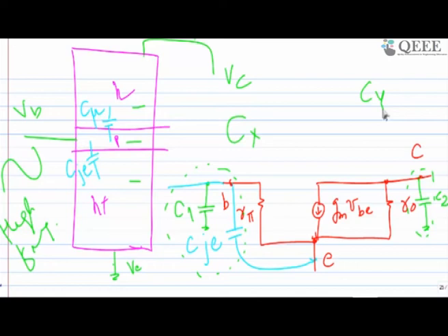So by looking at this model, you should now be able to tell that there are two effective capacitances, which means there will be two effective poles. So it's a two-pole system. There is not only one pole, and not three poles, it's two poles. So these things can be useful to find out how many poles there are and how many bottlenecks are available in your system to limit the speed. I would like to invite you, if you have any question,